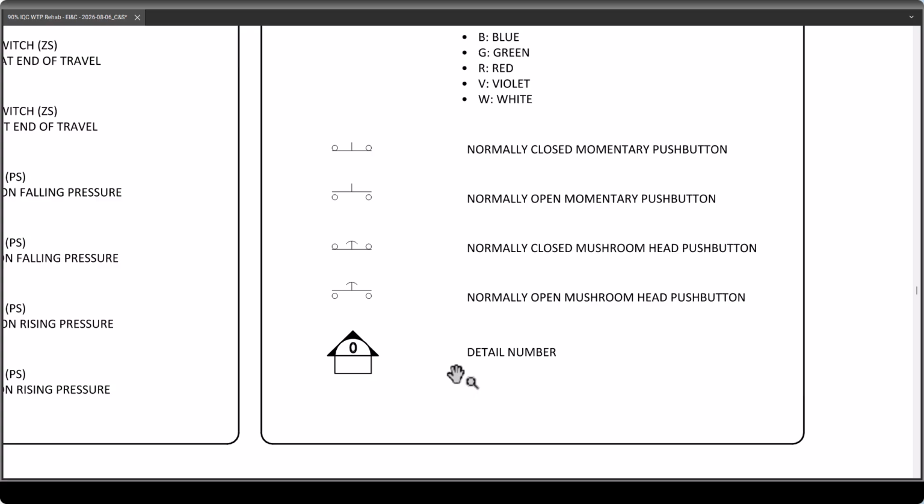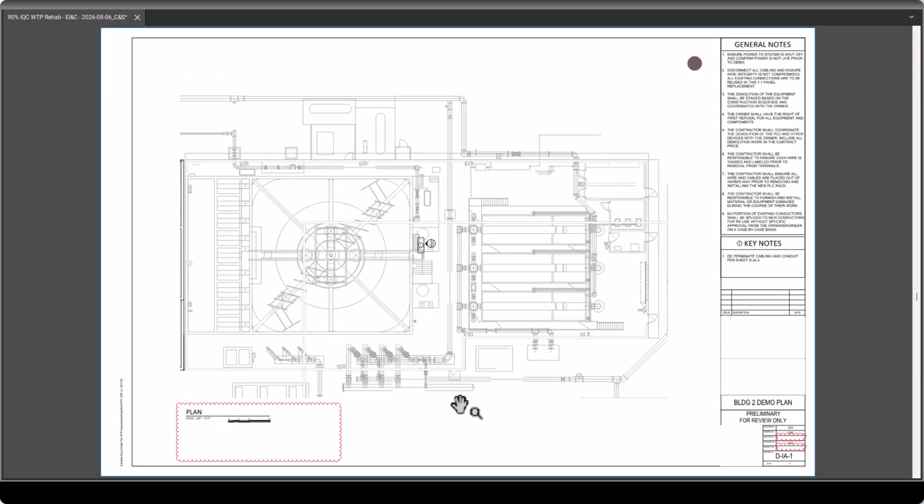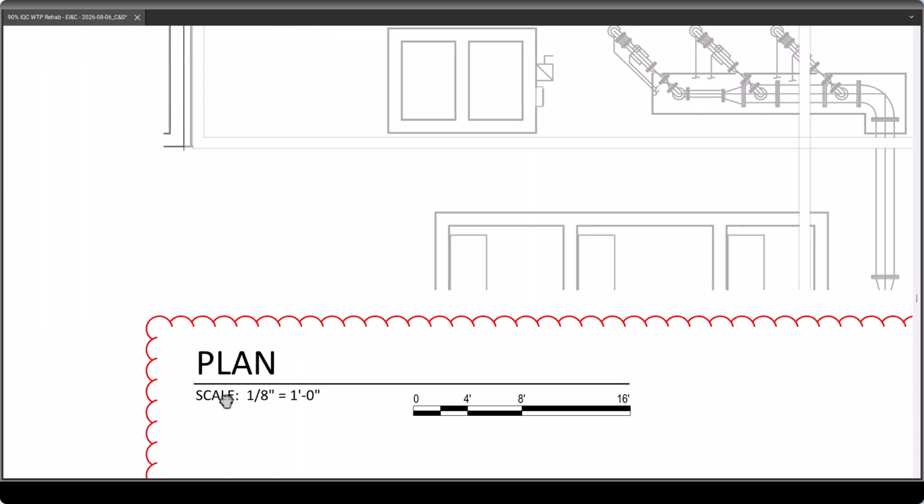And for people on YouTube, what I mean by the G sheets in our industry, we present general sheets, architectural, structural, civil, HVAC, plumbing, electrical, process mechanical, and then INC drawings. Not necessarily in that order, but it's all one single package. And it's going to be anywhere from 200 to 1200 pages of drawings just like this. So when I say G sheets, it's the general sheets that define what a detail number looks like, what a header looks like, what basic things like this look like.